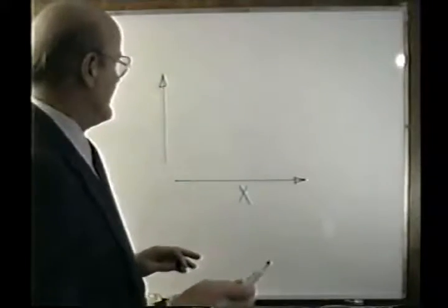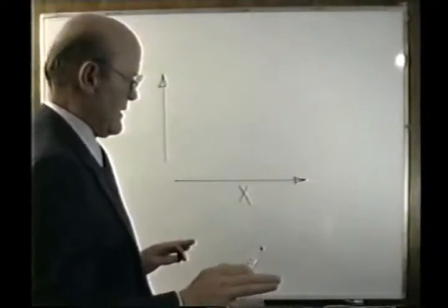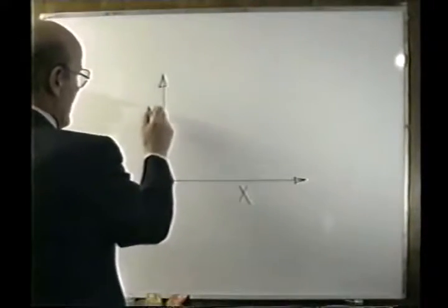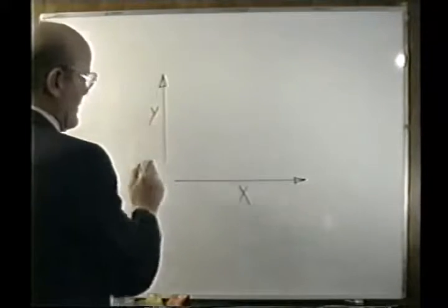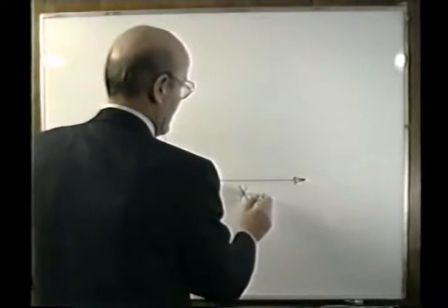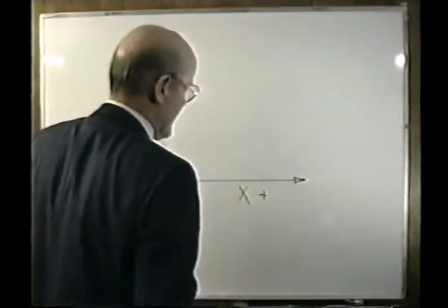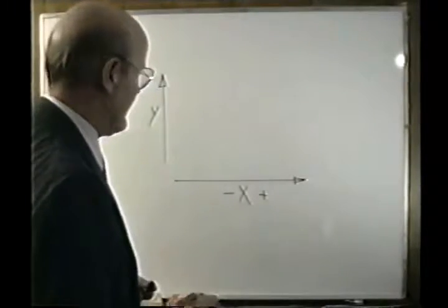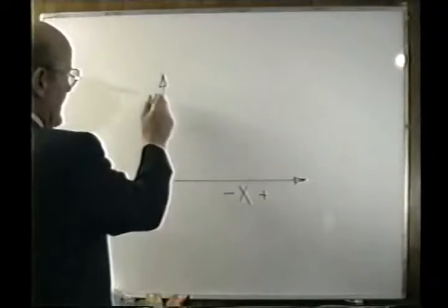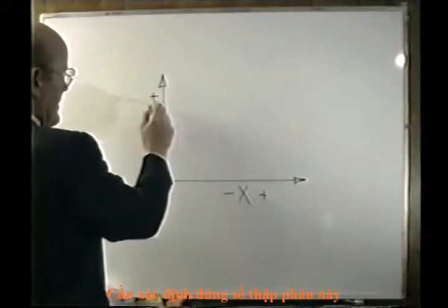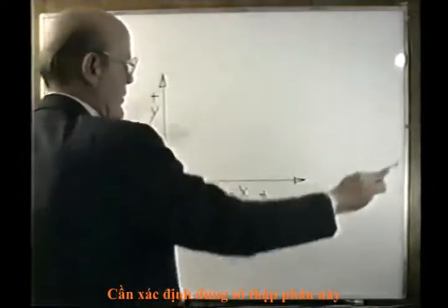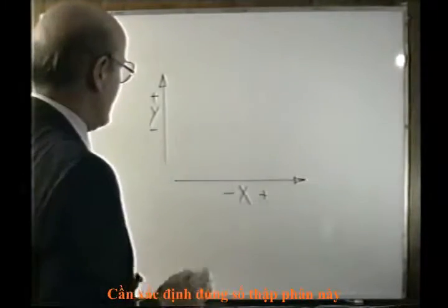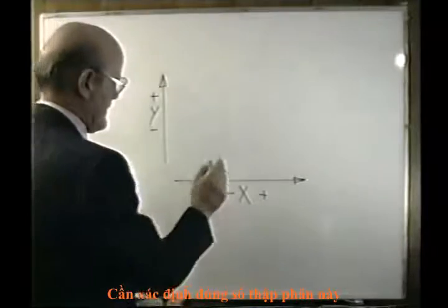In and out motion, on the machining center we just looked at a little while ago, is Z; side motion is X, and this motion would be called the Y direction. When the numbers get bigger, that's called the positive direction. When numbers get smaller, that's called the negative direction. And in this direction, numbers get bigger the further we want to cut in that direction, and they get smaller this way.